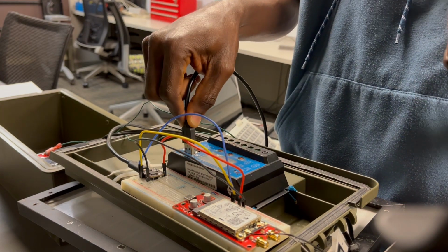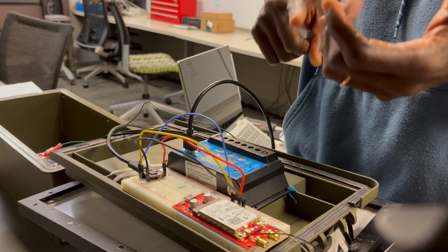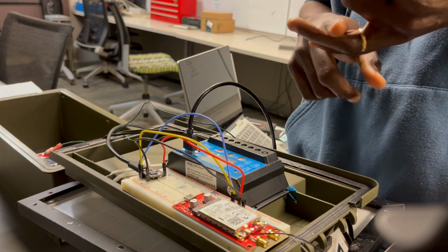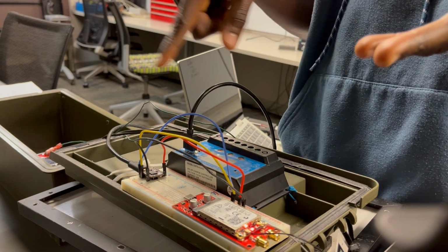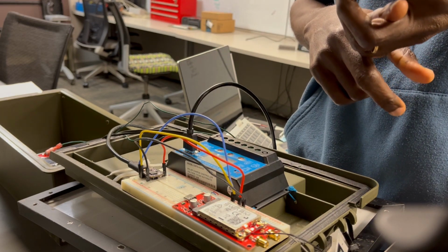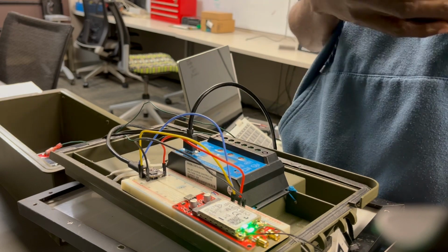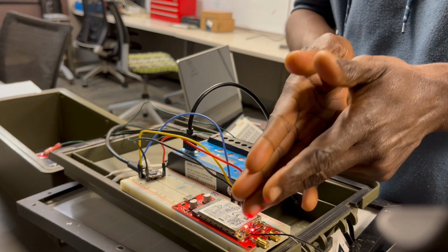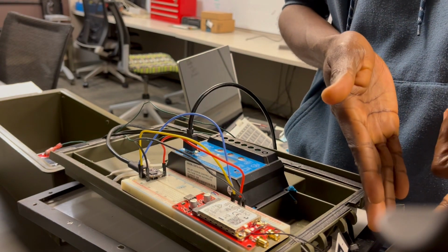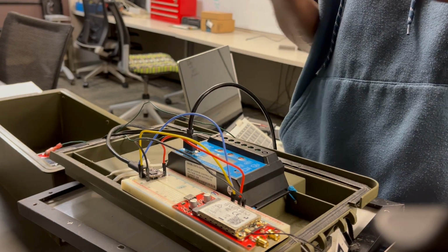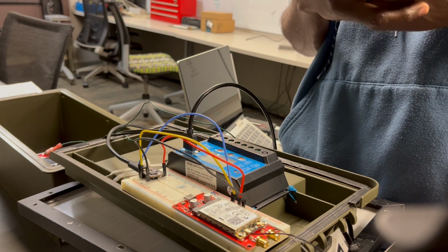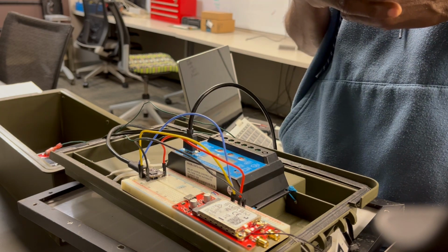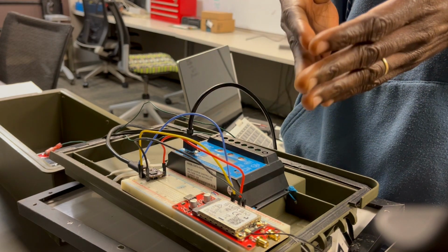So three things: configure the Wi-Fi, configure the web server, and configure it to send and receive serial communications with the Swarm board. And this type of solution is key because the Swarm board and the antenna need to be in the open, and to send information from you, the human being, to this device, you can't always be in the open.